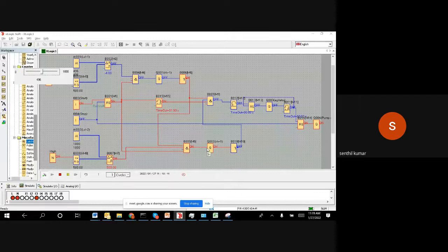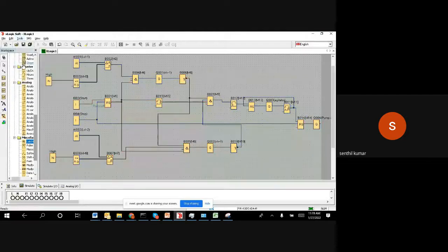However, I find there was something not correct. The agitator took a start before I closed the second valve. What's happening is that it's a fast scanning, and that is happening. So the logic is not so perfect. To fix it, I'll go here. The same timing, like 1 second timing, we can implement here. Okay, right. Let us do this.